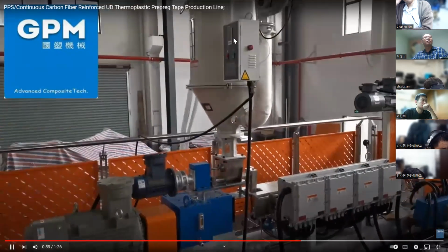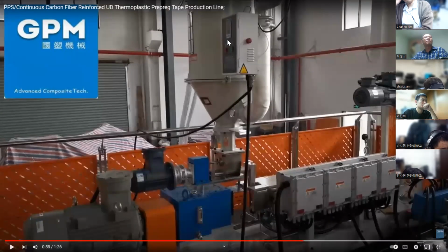And this is a resin. This is the thermoplastic. Thermoplastic will be melted here on the top, and there can be some pellets or any form of the thermoplastic resin. Resin will be melted. As you can see here, this is a screw. I guess the screw goes this way. So depending on the thermoplastic, we will have different temperature stages, like 300, 320, 350, and finally fully melted resin goes into